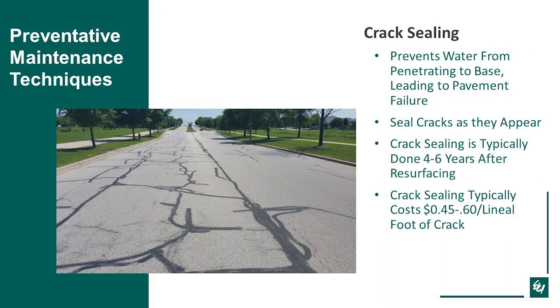Crack sealing, everybody's I think familiar with this one. It's utilized pretty much everywhere. It prevents water from penetrating the base. You're going to want to seal the cracks as you see them. A lot of municipalities will have a crack sealing program to go out and crack seal right after the winter, find cracks, seal them right away. It can't hurt. You're going to prevent that water from getting to the base, and that's what you want. You want to try to stop that as soon as possible.